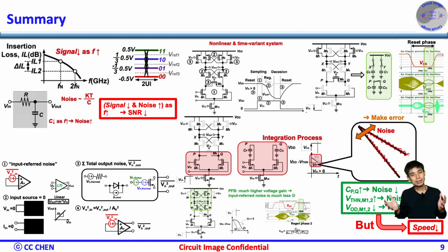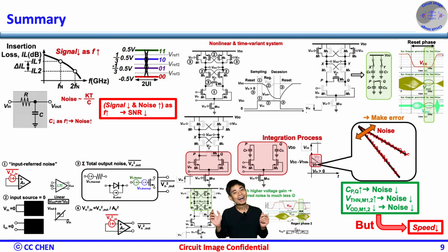Therefore, we must optimize the sizing through a SPICE simulation later to get the noise analysis precisely. Lastly, the regeneration phase would have little contribution to the input referred noise of the sampler, and we just need to make sure not to oversize those latches, which would raise self-loading capacitance and degrade the speed.